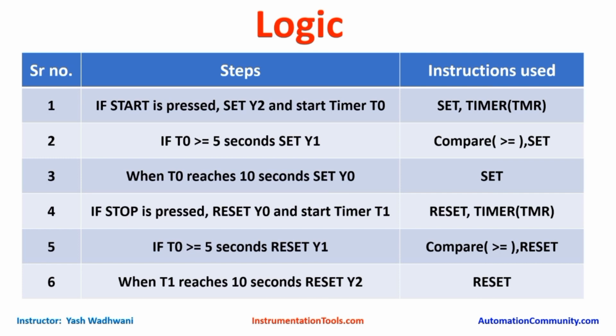We will see what is the logic required to create this project. First of all, if the user presses this start button, it should set my Y2, which is my output conveyor. My output conveyor should start instantaneously as the start button is pressed, and it should also start one timer T0. For this I have used two instructions: first is the set command and another is the timer instruction.